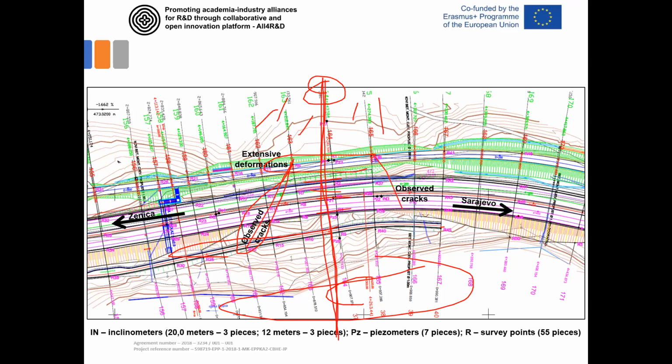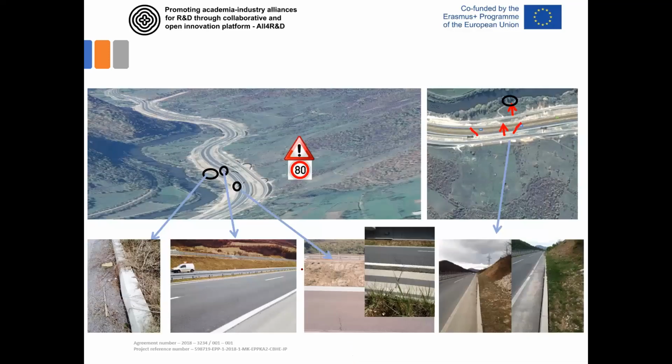And these points all indicate the geodetic survey points. An inclinometer is located one here, the other here. The one is in the stable area, just to see if there's some difference between this potentially unstable and stable area. Piezometers here. All the measurements were concentrated in this typical central cross section to define it as well as possible.